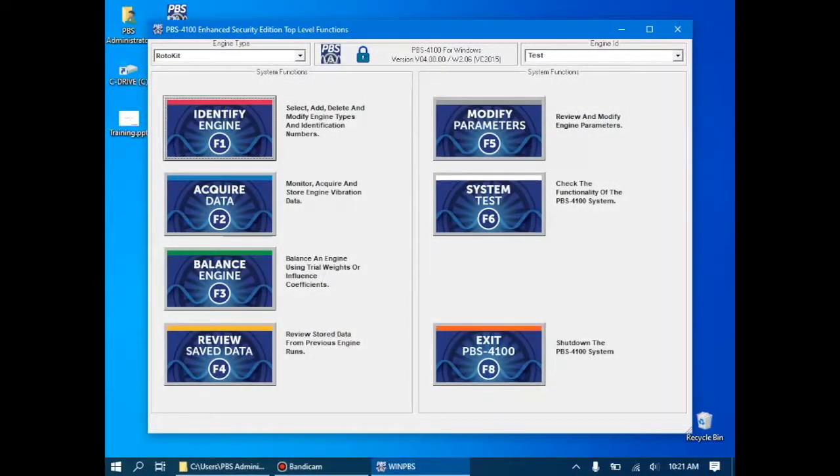Everyone, and welcome back. In the previous video in this 4100 series, we looked at completing a basic vibration survey and how we can take that vibration survey information, review it after the fact, and determine if an engine can or cannot be balanced. We determined in the case of our roto rig, which we use for demonstrations, we have a pretty good shot at completing a basic vibration balance. In this video, we're going to use that acquired data to complete a trial weight balance for the engine.